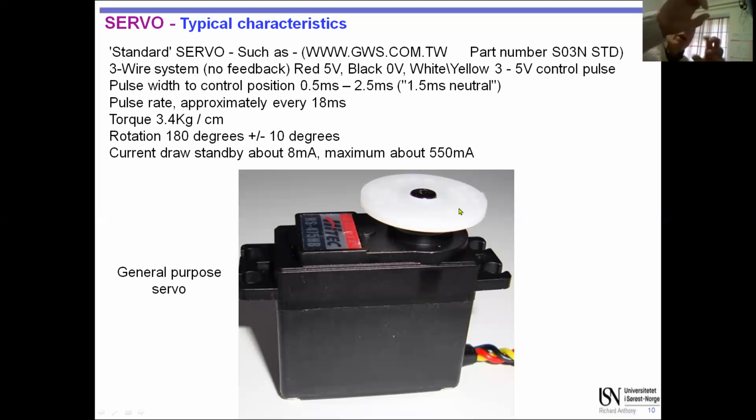So your servo is like, there's your disc, and you have the string attached to it, and you want to raise that piece of string by rotating your servo, then if you attach 3.4 kilograms, 1 centimeter from there, this would raise that. That's a lot. That's 7 pounds in English, old weighing technique. 3.4 kilograms on this little thing. So you can imagine quite a heavy arm of a robot could be moved with this.